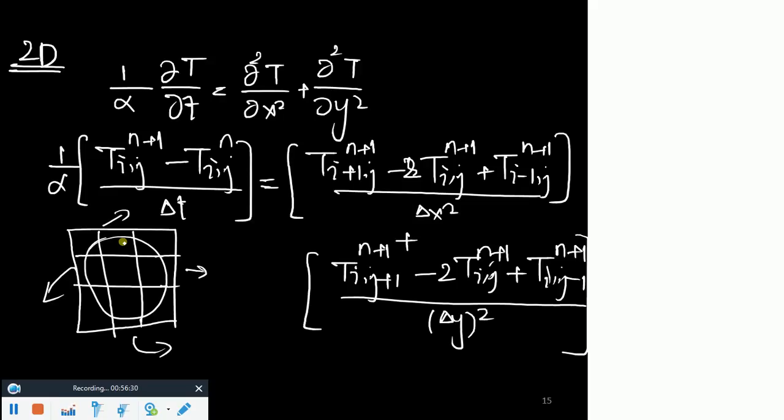Okay. Any problem about this implicit scheme? Now you see, for example, did any one of you experience any kind of Fluent or let's say ANSYS or any other software? You have used that? Okay, you might be selecting those numerical techniques. This is first order, this is second order. If you go for a few terms, let's say unsteady term and the momentum term, diffusive term, right? Once you select those terms, you have to be very careful about the stability technique.